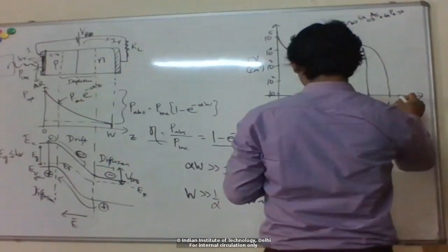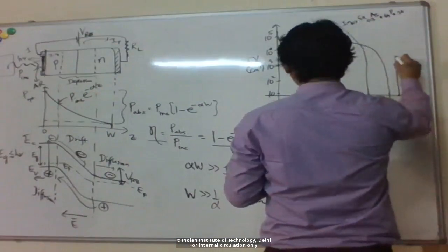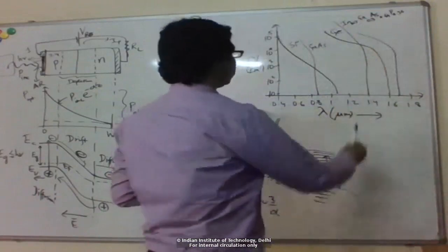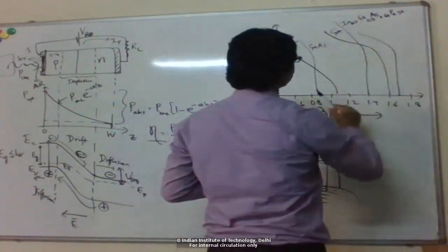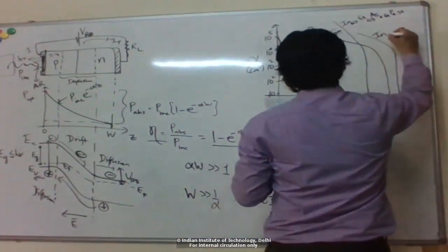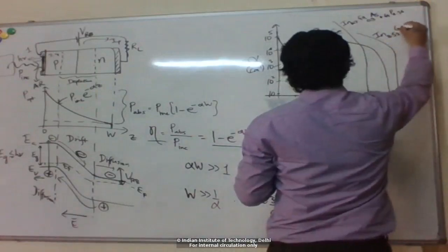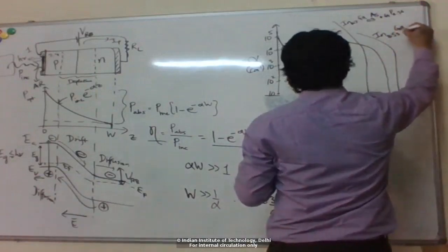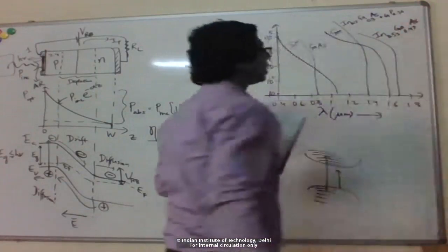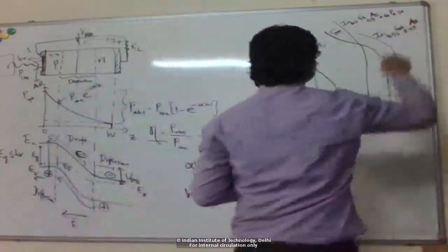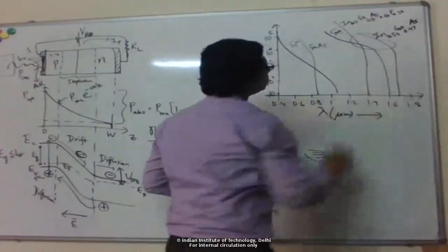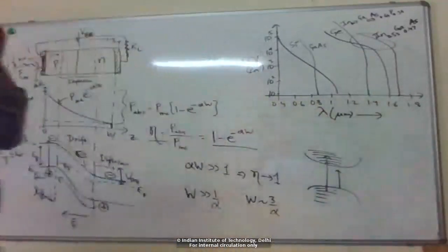If you want to detect across the telecom band of interest, typically 1.3 to 1.6, 1.65 micron, then we go for these InGaAs photodetectors: indium 53%, gallium 47%, arsenic 100%, no phosphorus. That enables me to detect in this telecom band of interest.